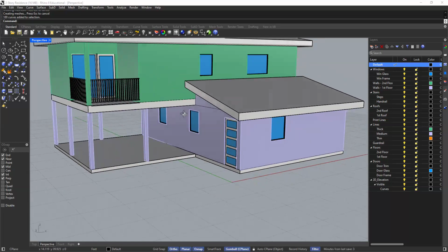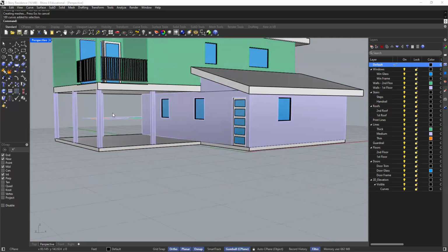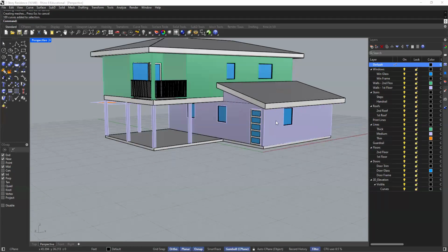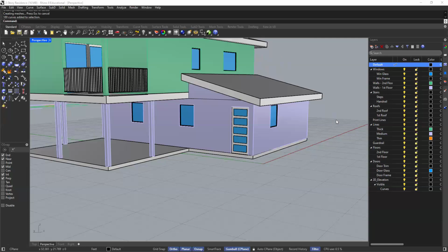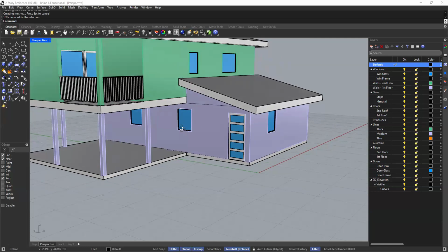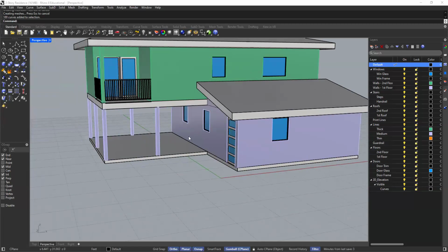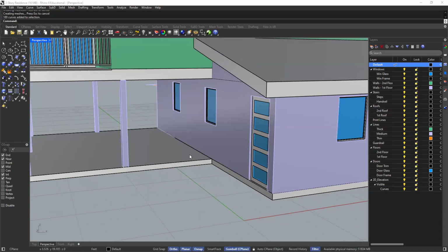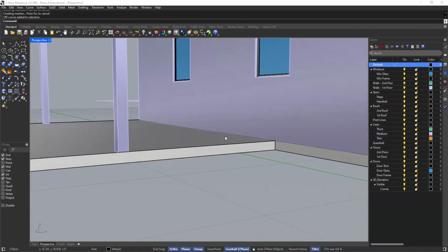Now, if you're not familiar, the term floor plan refers to a horizontal cut that cuts through a building. Okay? Vertical cuts are known as sections, but horizontal ones are known as floor plans. And these horizontal cuts are typically taken 4 feet above finished floor. Finished floor just refers to the top layer, the top material that we step on.